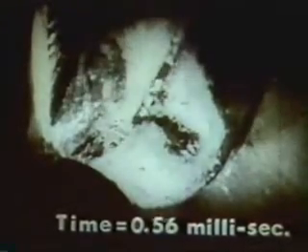The cyclic nature and extent of the rear channel cavitation is more evident in the following still photographs with reference marks. Cavitation is estimated to be blocking 60% of the flow channel.